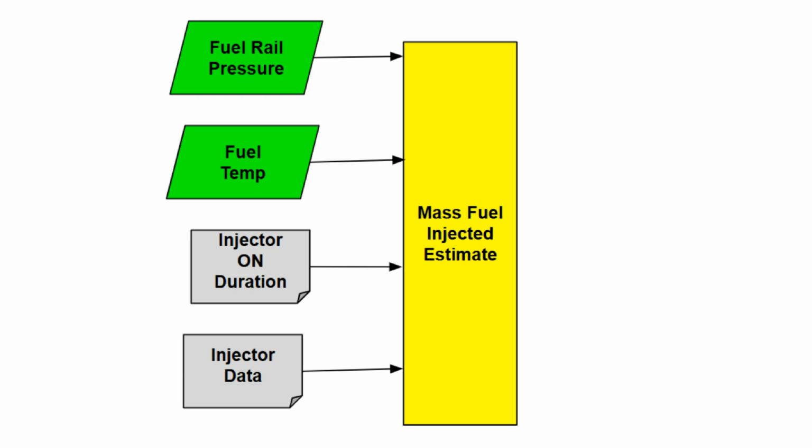This empirical data includes the flow characteristics for that particular injector part number, which is provided by the injector manufacturer. And then this is stored in the ECM as a lookup table. The IQA injector quantity adjustment strings, those things that you have to change when you change an injector on some engines, may also be used to fine-tune the injector flow rate for each specific serial numbered injector to take out manufacturing tolerances in the injectors.